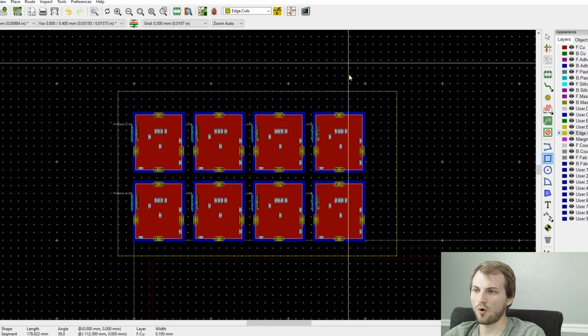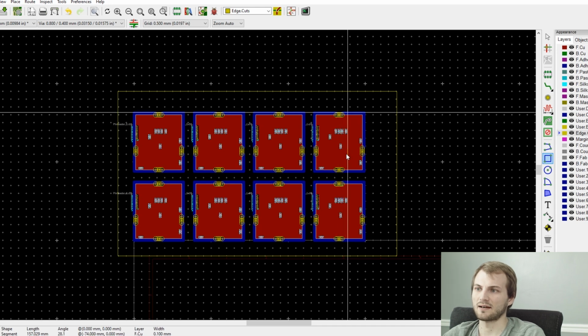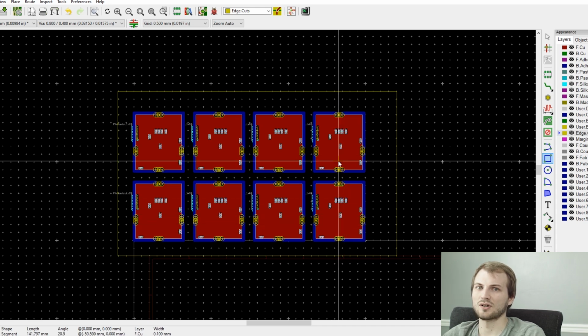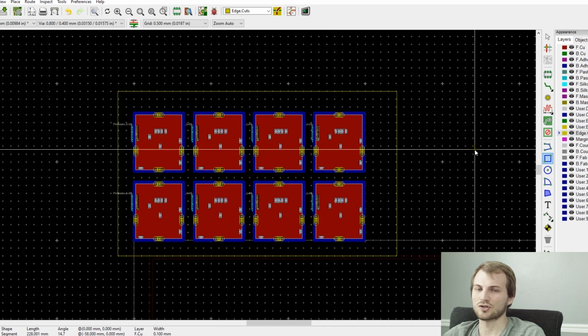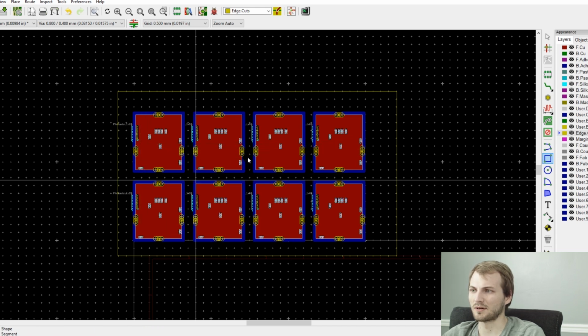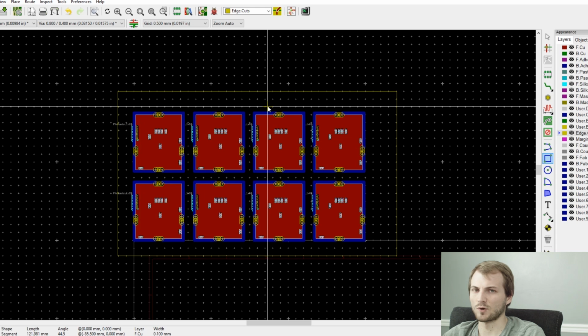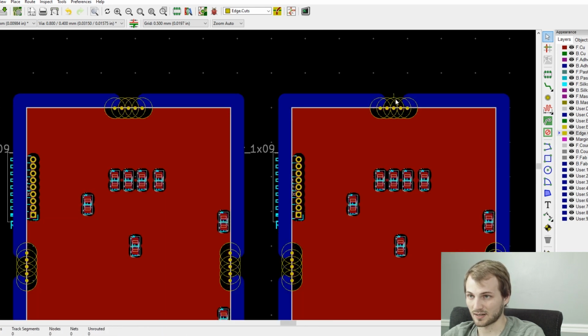And these you always want to do perpendicular to the long side of the board, because it's going to go in the assembly line left to right, so you have the least amount of board unsupported. I know that's kind of hard to explain, but you'll see once all the panels are in, it makes a lot more sense, or at least it should make sense.